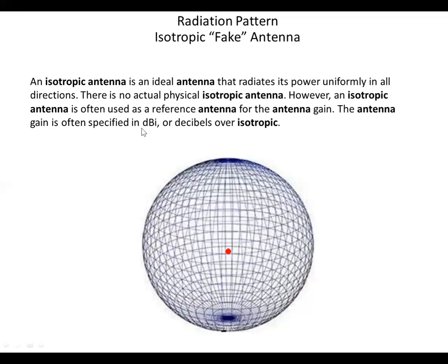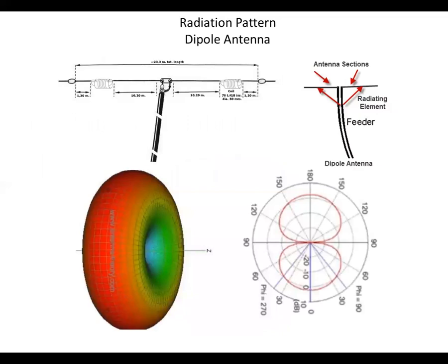And when you start looking at antennas, if you haven't already looked at VHF and UHF, you may see them in the catalogs and on the websites talking about their gain. It'll either be dBi, for reference to the isotropic, or a reference to a dipole, so it must be dBd.